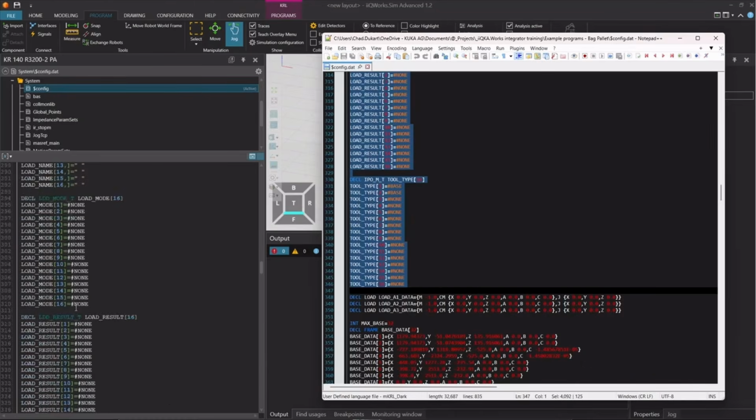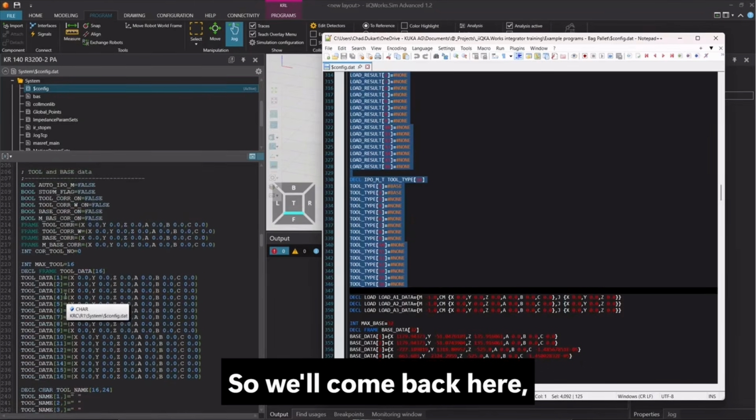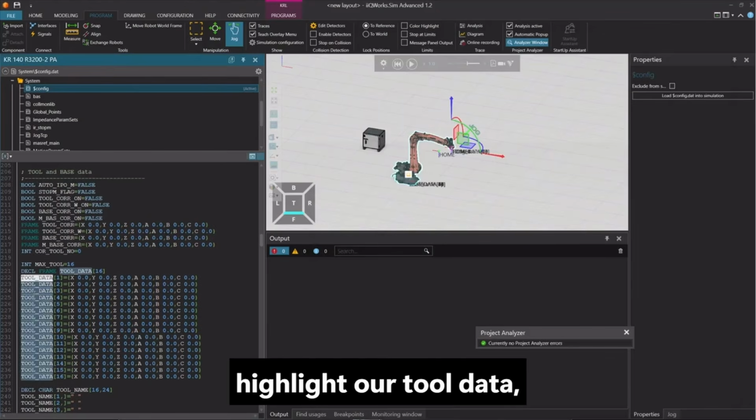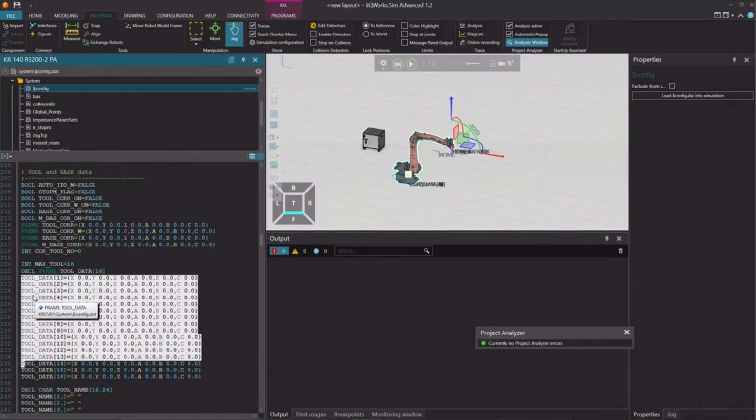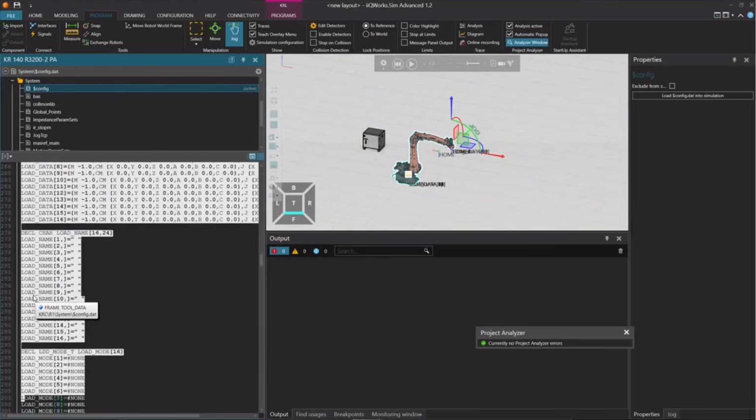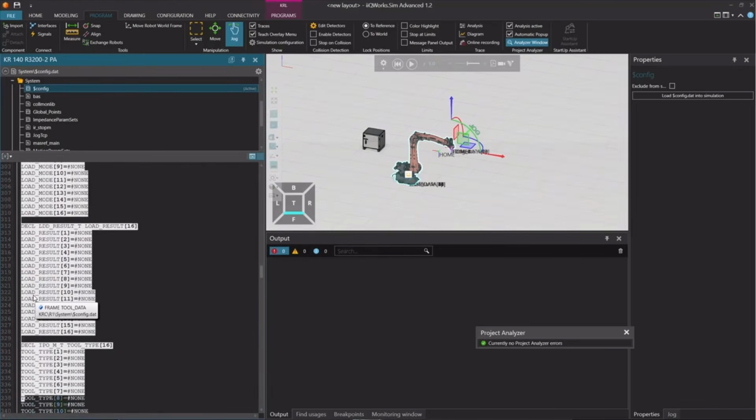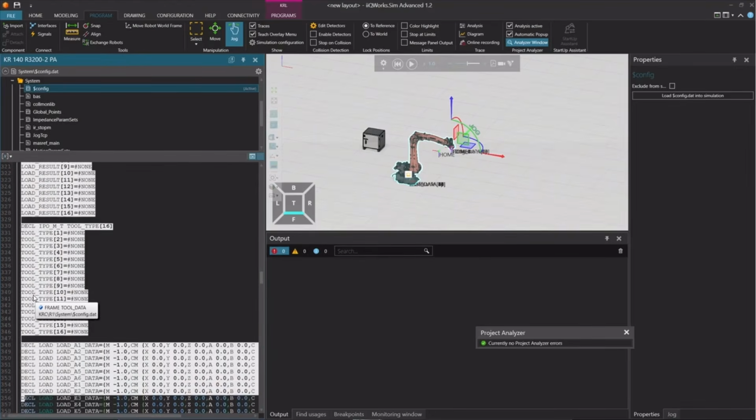You may notice additional variables in the newer system. If these variables are missing or mismatched, the system will report errors during validation. Paste the selected tool data into the new config.dat file, align it correctly, and remove any extra spaces.